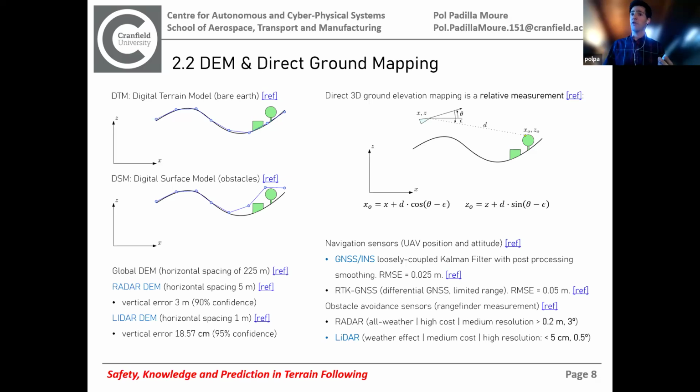And there would be several options. You could try to implement a SLAM technique here, for example, in which you simultaneously locate yourself and map the environment at the same time. Critically, the SLAM technique relies on landmarks. So if you must rely on a landmark, that means you already have a little bit of knowledge that you're going to encounter certain landmarks and you're going to build your map around them. And then if you do several passes over the same place, you can improve your estimation of your environment.